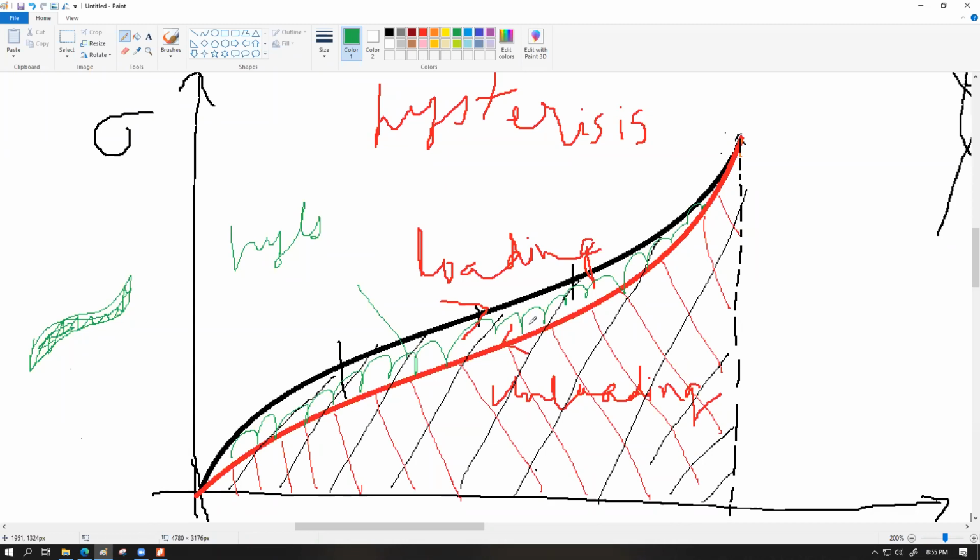But let's say if you want to make a solid rubber made bed for a pole vault jumping scenario, you would prefer to have that rubber material to have a really thick hysteresis loop. The idea is that when the pole vaulter will fall onto this rubber substance, they are gonna convert all of their KE and GPE into the stored energy. But whenever the rubber material is going to come back to its original shape, it is going to retain most part of that energy within itself as heat and give a much smaller fraction of that energy to the pole vaulter, so that they're not going to be catapulted back into the sky. Are you getting my point?